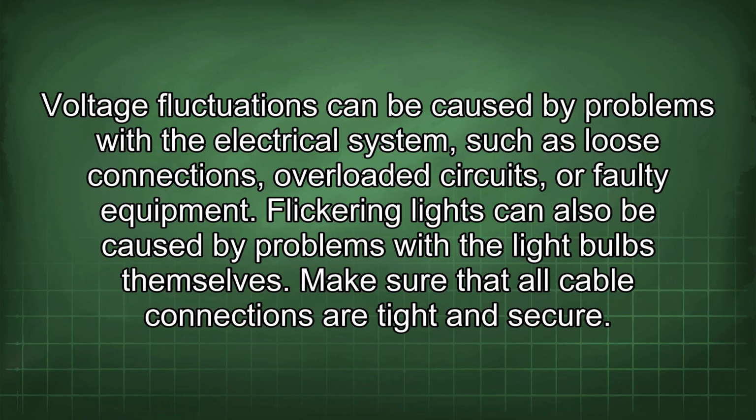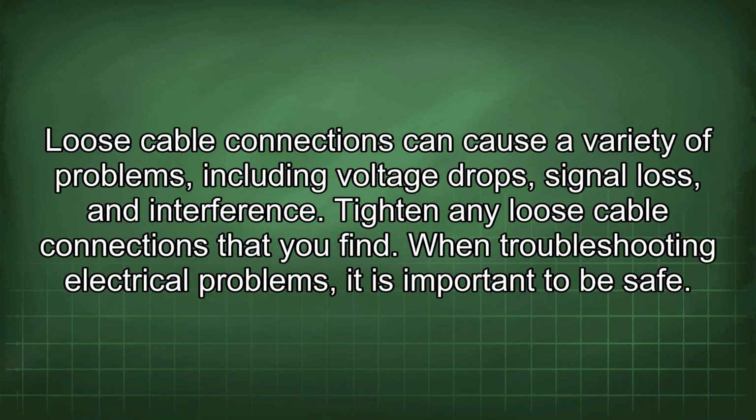Make sure that all cable connections are tight and secure. Loose cable connections can cause a variety of problems, including voltage drops, signal loss, and interference. Tighten any loose cable connections that you find.